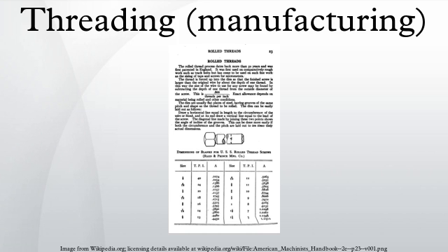Thread forming and thread rolling are processes for forming screw threads, with the former referring to creating internal threads and the latter external threads. In both of these processes threads are formed into a blank by pressing a shape tool, commonly called a thread rolling die, against the blank, in a process similar to knurling. These processes are used for large production runs because typical production rates are around 1 piece per second.